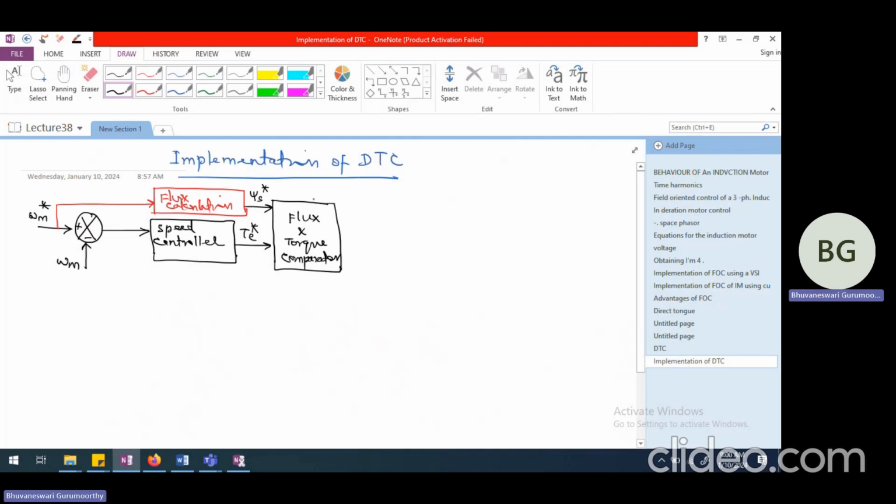The same way, if the torque is less, then you might have to push, because if you look at an induction motor, you have psi S here and psi R behind that, closely following it. Whatever is the angle between these two, we call this gamma. And we said that psi S cross psi R is psi S magnitude multiplied by psi R magnitude and sine of gamma.